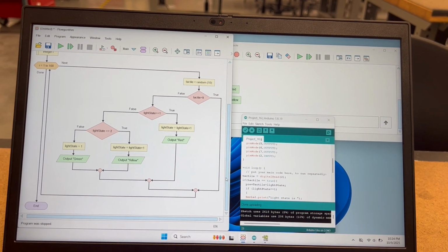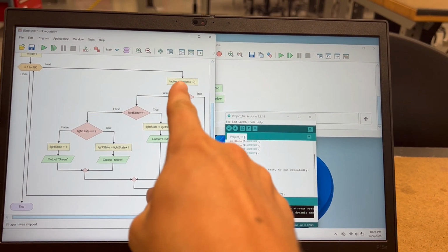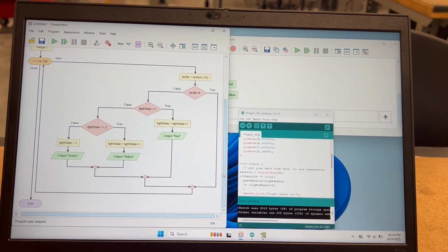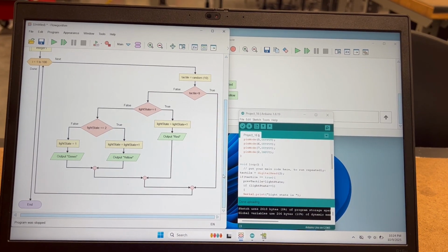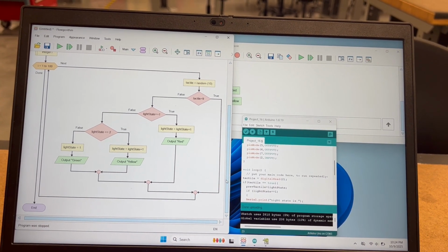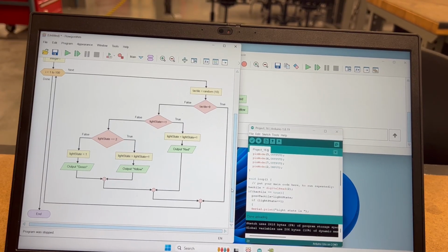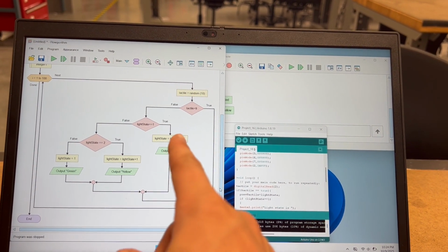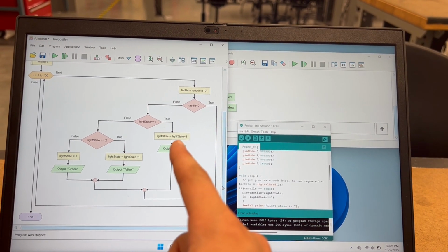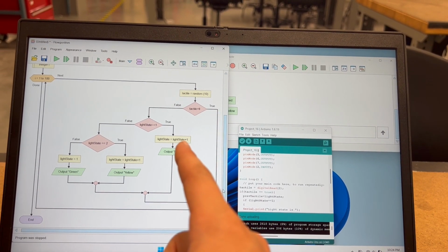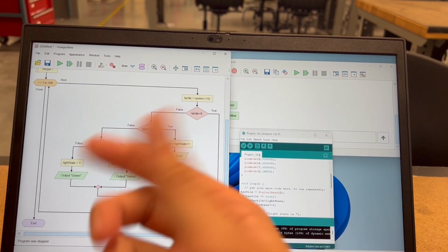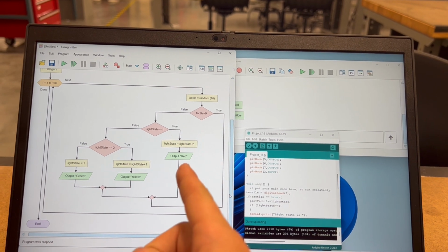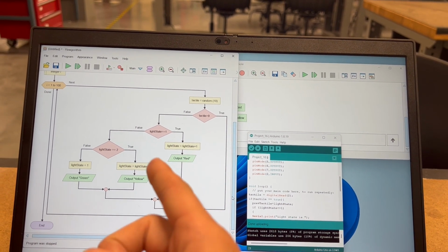in the for loop, this is basically saying that if we get the 10% chance of the button being pressed, then the light state is equal to 1. And then we set the light state value equal to the light state value plus 1. So that should be 2 now. Then it would output the red, or turn on the red light.